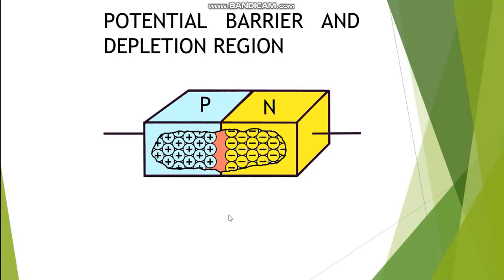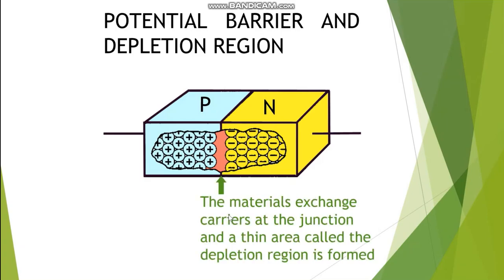So here we have an N and P-type material. When you take N and P-type material and put them together, you've got a positively charged semiconductor material and a negatively charged semiconductor material. The negatively charged has electrons that are free to move. And you have the P-type material, which has an excess of holes. What ends up happening is diffusion, where the electrons move over to the P-type material, filling those holes, leaving behind holes in the N-type material. So essentially it almost flips polarity.